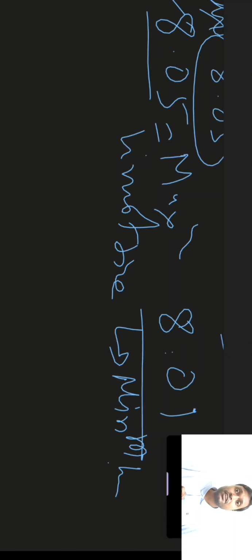We also studied in the previous class that the same physical part which behaves as a hole for one assembly may behave as a shaft for another assembly, and for this we took the example of the mobile phone, which behaves as a hole for the charger connector, and the same mobile phone behaves as a shaft for the cover of the mobile phone.